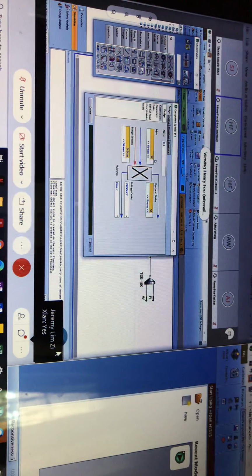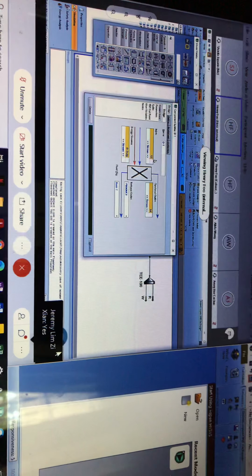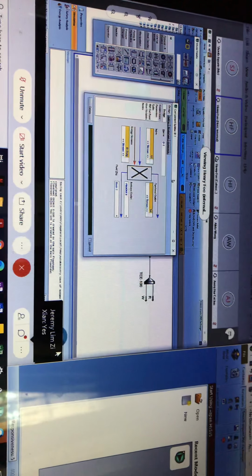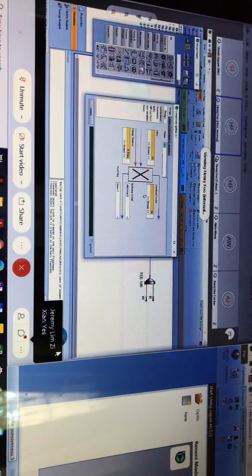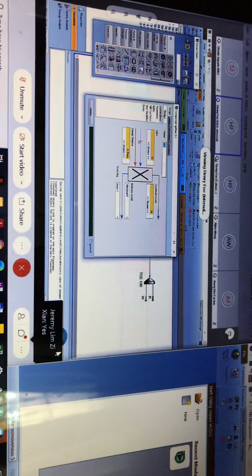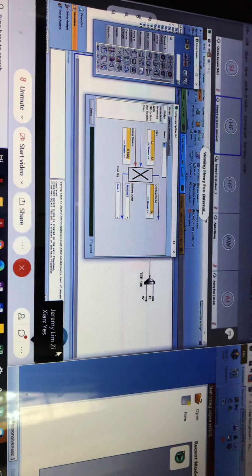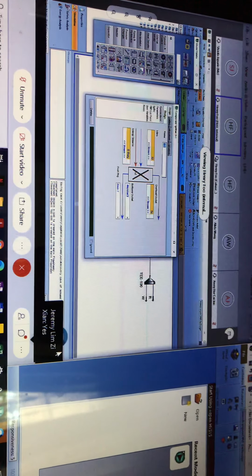Okay, for the component splitter, we can go back to what has been listed in step 7 of the questions. So we change the name to D1. We define the inlet as 2. We define the overhead outlet as 4. We define the bottom outlet as product. And we define the energy stream as D duty. So we define all the inlets and outlets for this component splitter.